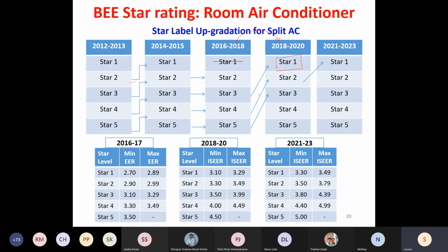Okay, and then these two, star rating 4 and 5, which were earlier still coming under the category 5, they were now able to differentiate those highly efficient air conditioning systems from the other ones. So let's say you have an AC which gives you 5 as the COP, and earlier the rating for star rating 5 was 4 COP and above. So 4, 4.5, 4.7, 5, everything was clubbed into 5-star. Now you have a clear idea which AC is more efficient and which is not.